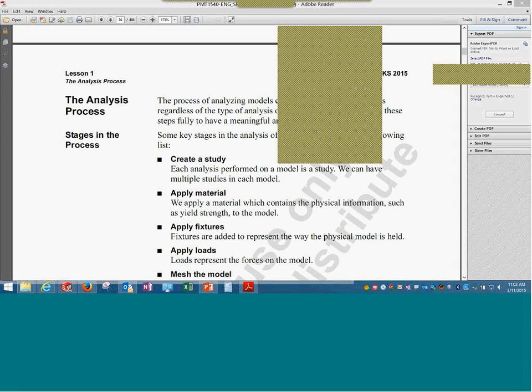Plastics' algorithm is the finite volume method. It is more of a CFD algorithm. I observed, on the same lines, that even the flow simulation algorithm is equally strong. So what we use in simulation is a structural finite element method meshing, whereas what is done in plastics and flow simulation is more towards another method called the finite volume method. So you can imagine the huge difference between these two algorithms.